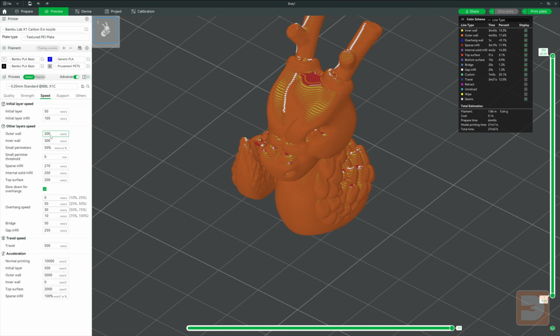It's also worth noting that the theoretical speed limits are different depending on your layer height. Your printer can only successfully heat up and push out X amount of filament per second, depending on your printer and the material. If you're printing at a 0.2mm layer height, your extrusion will require twice the volume of material per second as if you were printing at the layer height of 0.1mm. As a result, depending on the variables at play, such as your printer, the material you're using, and your existing settings, you may want to print slower at thicker layer heights.